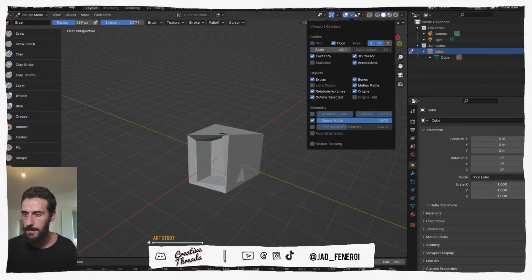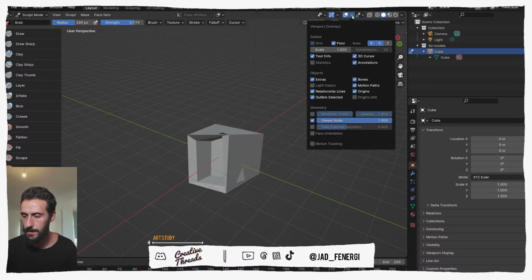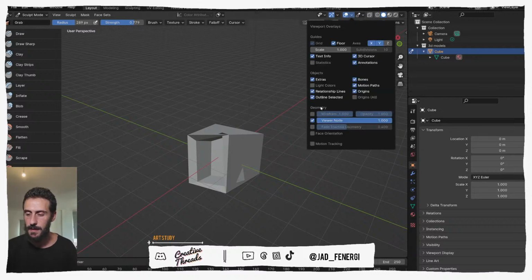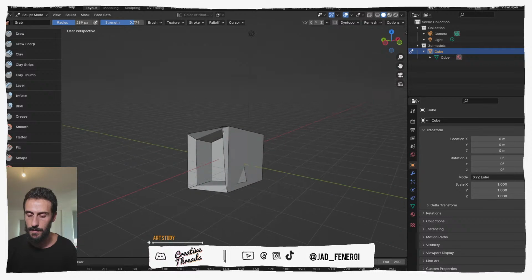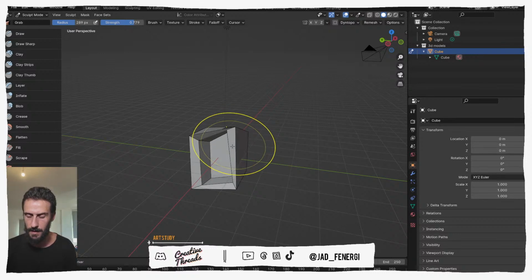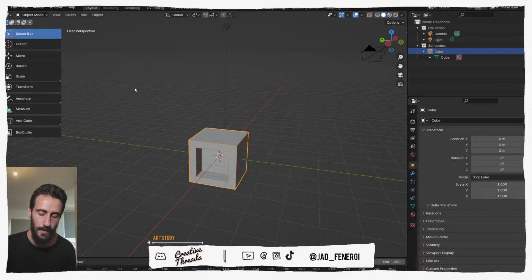And I think the wireframe is somewhere. Yeah, so if you press here, you have something called viewport overlays, and here you can turn on the wireframes for the viewport. Shift is to smooth everything, so I smooth the whole thing and it's collapsing on itself. Again, I'm not gonna go too deep, just like 10 minutes. We've already been through half of it.